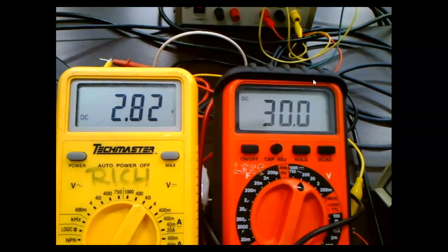This is the resistor. So I'm going to take 2.8 volts and divide it by 1 meg. This is across the diode. This is what we're going to use to calculate the current with. Everybody okay? So there's current flow through the diode. Right off the bat, we know there's current flow through the diode, even though it's reverse bias. This is the current, right?